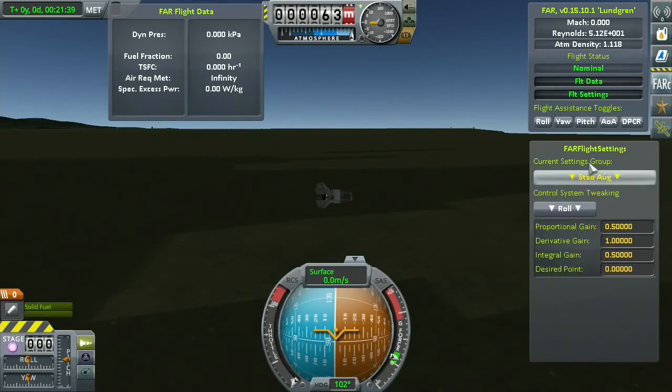The next page is tweaks to these. All 5 buttons have a page of their own. The first 3 of these are what is called PID controllers. PID is an abbreviation made up of a P, I, and D, where in turn P is for proportional gain, I for integral gain, D for derivative gain. And then the 4th and even more important component is the mapping to and from the PID controller. In this case, the wing leveler, we get the bank angle as an input, and the PID controller will apply these constants in a way that we will look at later in the next video.